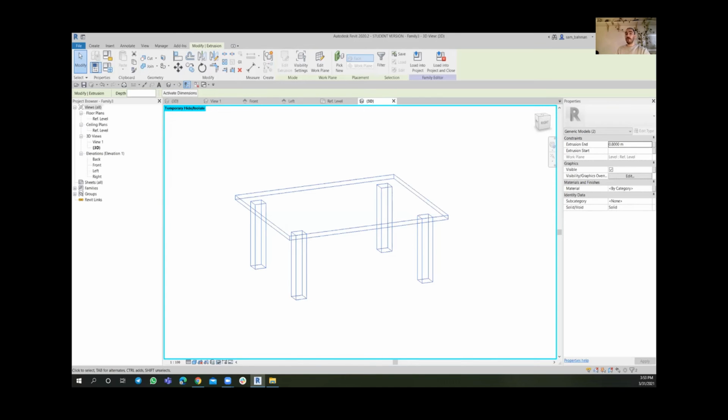To make sure that we would always be able to set up the same material parameter in an actual project without the need of going back and forth to that template, we would be able to set up a parameter. So how we set up a material parameter is to select all what you have. And it's really important to select only those parts that you wish to have the same material.